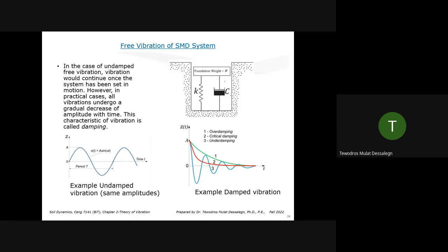We're introducing damping, because in reality, it doesn't vibrate continuously. At some point, the energy dies. We need to incorporate that concept in the model. And the mechanism where the energy gradually decreases, we model as a damper. So this third case is where we have the stiffness, and we're introducing a damper and mass system.